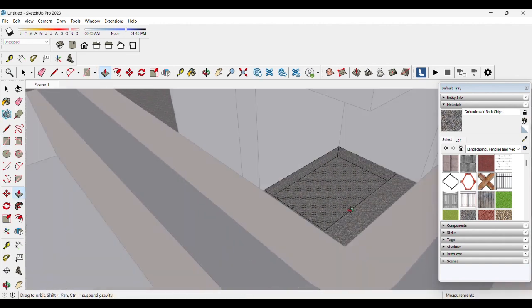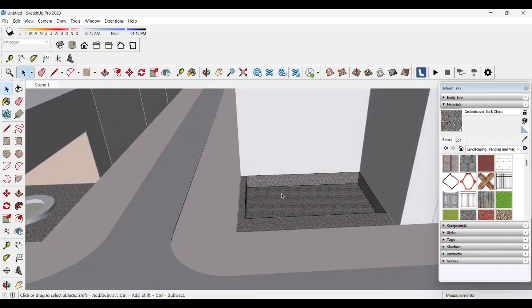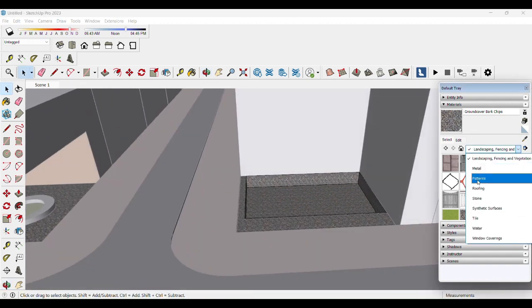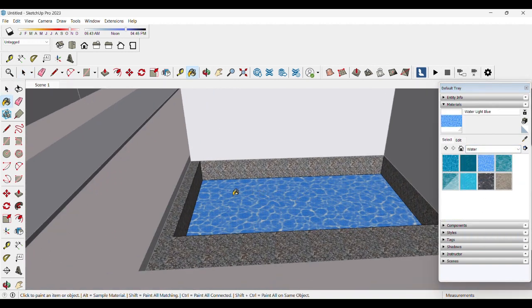Rectangle and push it back, and then we'll give that a water texture. We'll still increase the width of it outside. Let's give a supporting surface or a threshold outside. Select the surface, and the command is O for offset.